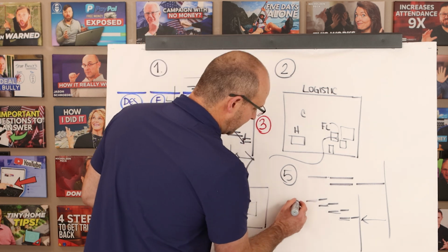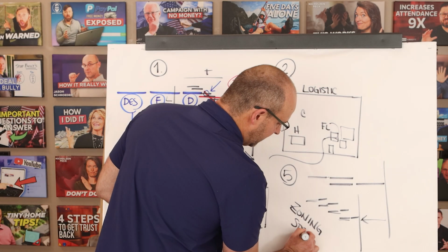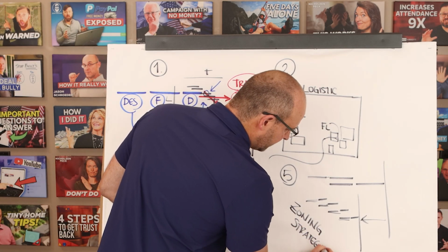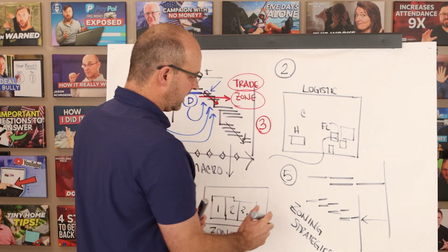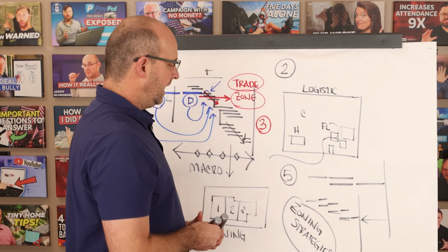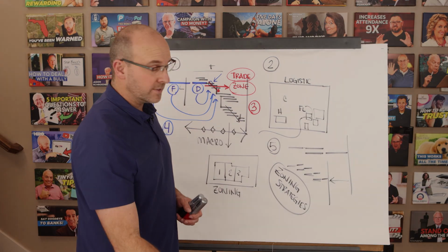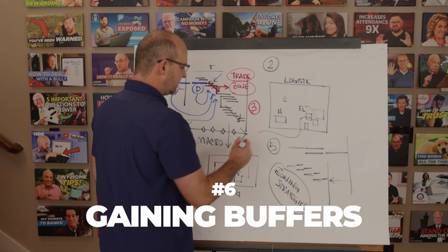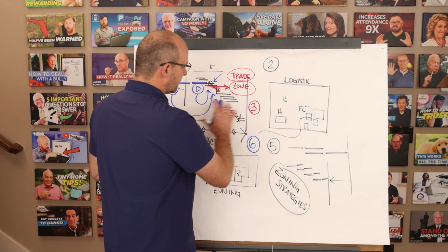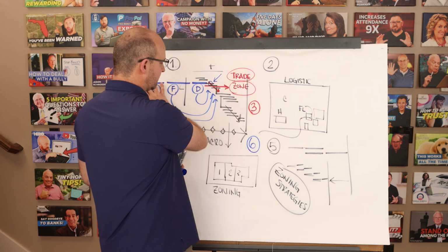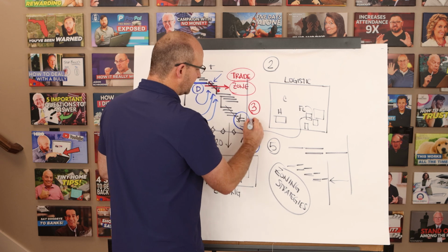And so what we need to look at are zoning strategies, right? If you want to speed up your project, when you come between the macro and the norm, meaning from your contractual promise to your production plan, you'll want to get smaller zones, and it will bring in your overall project duration for the purpose of gaining buffers. And that's number 6 that I want to mention in this video, is that we're bringing this forward, right? We're doing this planning, we're identifying our bottlenecks, we're designing to the work package, and we're rezoning so that we can gain buffers in the system.